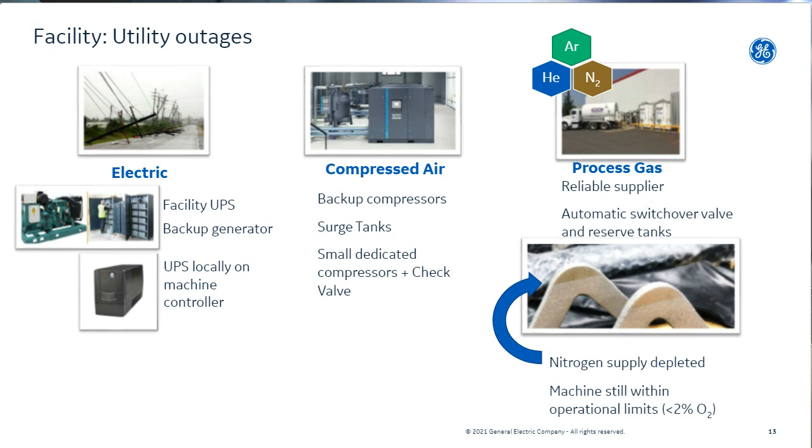Utility, talked about this. UPS and a backup generator is kind of your top tier. UPS, because even with the diesel generator, it takes time to fire up. So if you've got power loss, you don't get instant power. That UPS keeps you at your 400 volts, and then the generator kicks in and can sustain you as long as you need. At minimum, a little UPS on the computer is great.